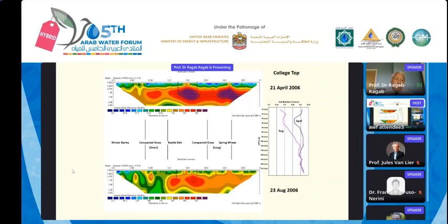Here you can see how heterogeneous the soil is, and the point measurements that we take do not really represent the heterogeneity of the system. But when you have a transect like this, then you can see the change in soil moisture depends on stratification, and also depends on the crop on top of that soil.